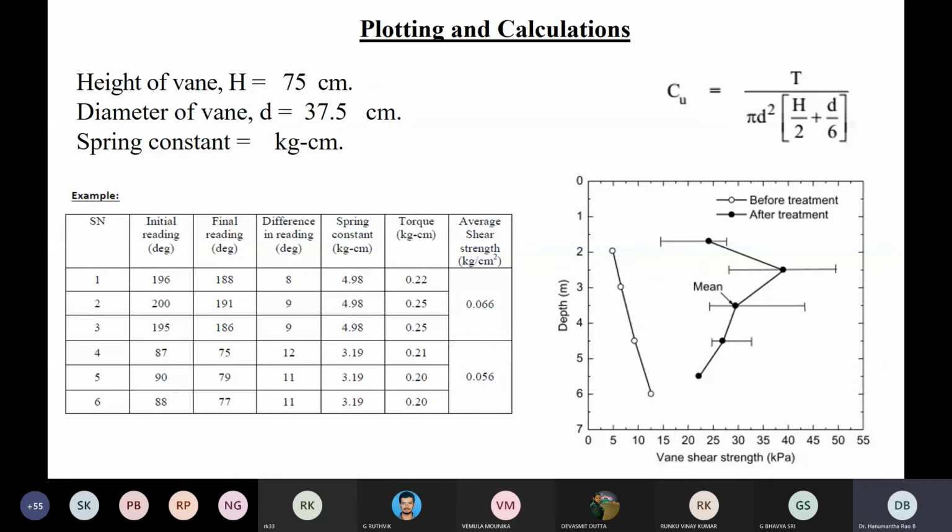Okay. So what was happening there? The volume of the solids remains constant, but only the water volume is increasing. So at the shrinkage limit, the soil is very stiff and high strength. But the same soil, with the addition of the water, turned into a slurry with least strength. So suppose you understand the mechanism of how the strength is decreasing: Vs, the volume of the solids, remains the same, the only separation being caused is by the volume of the water that you are increasing.